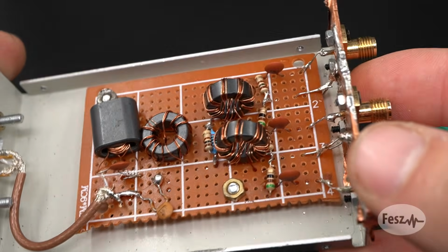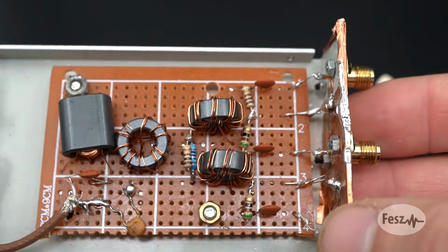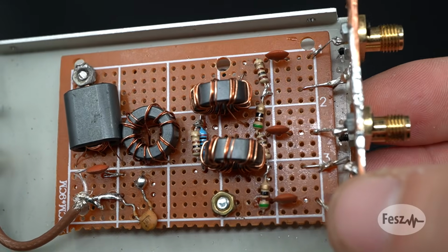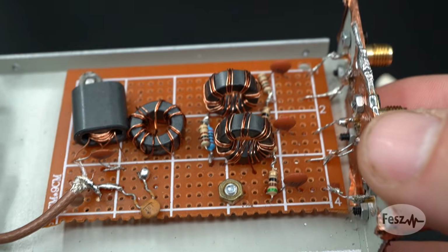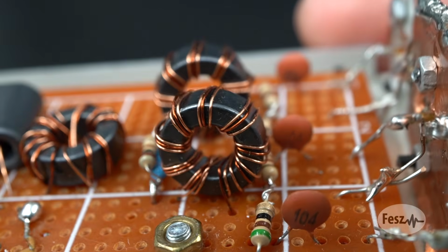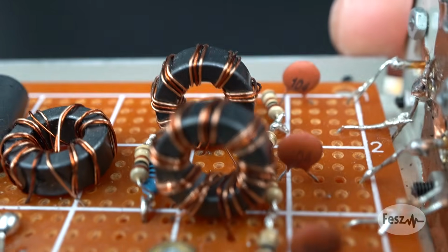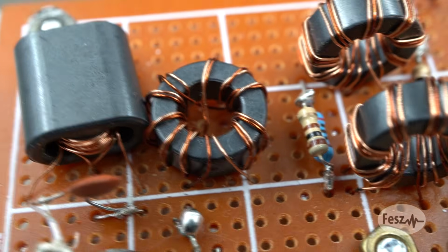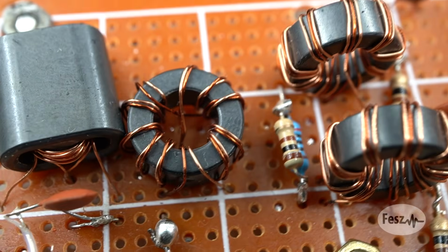This is the build circuit. For the board, I used the basic perforated substrate. This circuit should mainly work for the HF band, so it's a bit more forgiving. And I used toroid cores for the splitting transformers. This allowed me to make the windings nice and tight, so these are more or less one next to the other for better coupling.